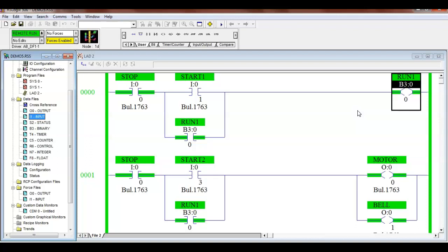It might have a name, but if you've got a relay coil that does not need to control an output, you're going to use a memory. And then I showed y'all that on that Festo diagram. How many memory coils did they use? I mean, they were up to 10. It was up to 9 already. But all those were in there for decisions to make sure this happened before that, and that happened before that, before something happens, right? You understand? A sequencing, setting up a sequence.